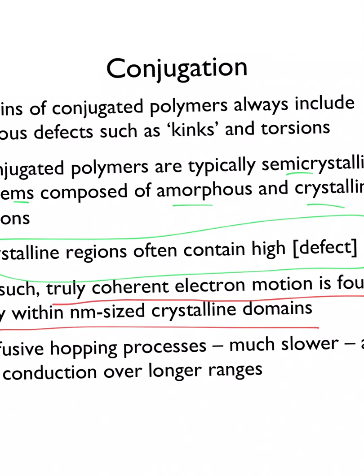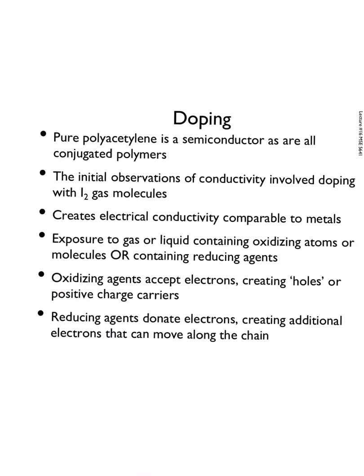So this mechanism that we like is a slave to crystals, because that's where we get this nice packing. Everything's orderly. This type of conductivity works great there. Everywhere else, which means all the amorphous stuff, which we know we always have, is limiting the conductivity. And so we have hopping between crystals, these nanometer-sized crystals, and that's where the conduction actually occurs, which is much, much slower than the perfect conduction we get within the crystal cells.